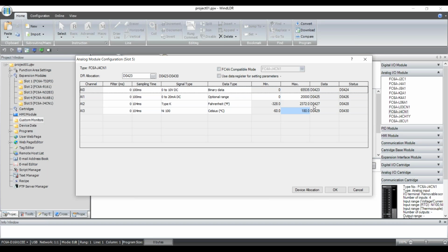So in other words, if here in my office the temperature is 73.5 degrees, I'm not going to see 73.5 in D427, I would see 735. So when we go to the PLC to actually get the temperature, we just need to convert the data type, and we've done this in the scaling webinar. We would convert the data in D427 from an integer into a float, and then divide by 10 to get the actual temperature. And that's true whether we're measuring temperature with thermocouples or RTDs. We do the same thing.